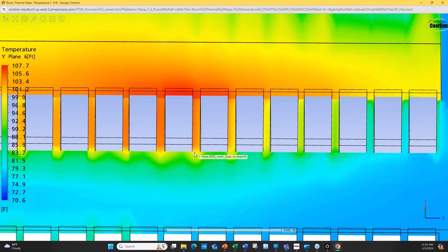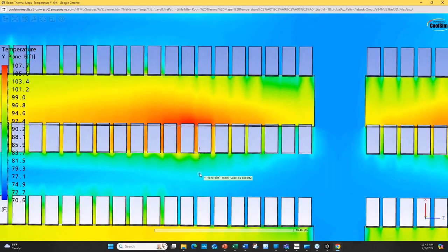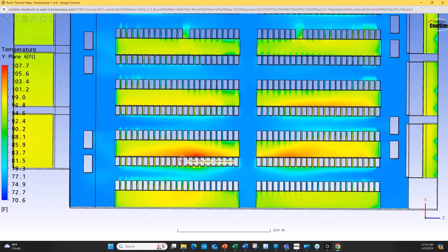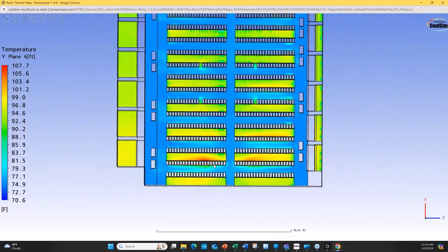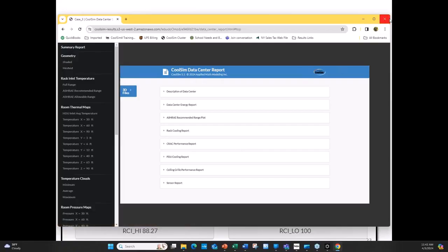Make sure all the blanking panels are in place, because the integrity of the design assumes that you have proper sealing between the racks and the hot and cold. And no different than what we learned back when we started working on IBM data centers a long time ago, right, Magnus? It hasn't changed. It's just that the density is now so high that this becomes more critical, if you know what I mean. Absolutely. Yeah.